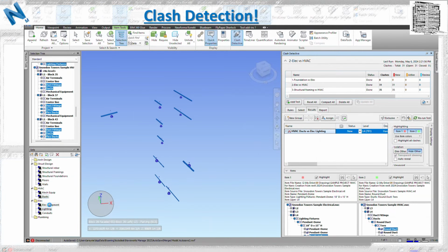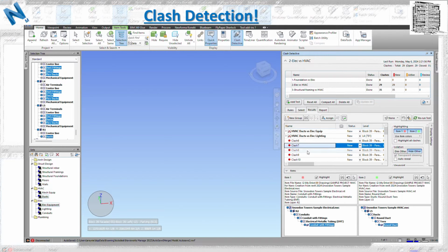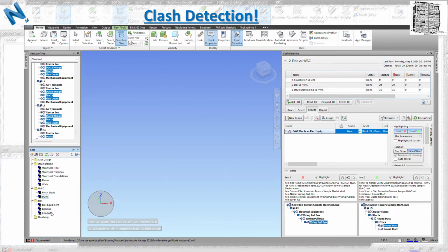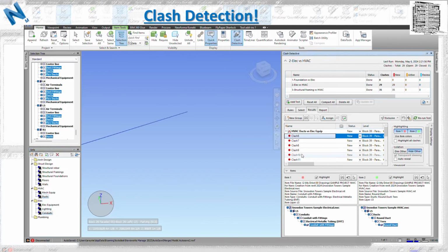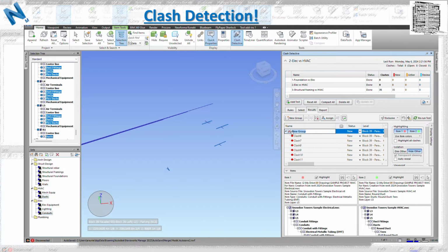else out. So this one, again, is a different technique that you can use when you are grouping your clash tests, and it's basically based on your need, like how you want to go through all of these. Like if you have cable trays, and you only want to look at the cable tray clashes versus mechanical duct, you can use the exclusive and put those two items in one clash group. And when you go to the meeting, if everybody wants to only look at that, they can look at that area only. So you don't have to have the lighting, conduit and other stuff versus the HVAC.